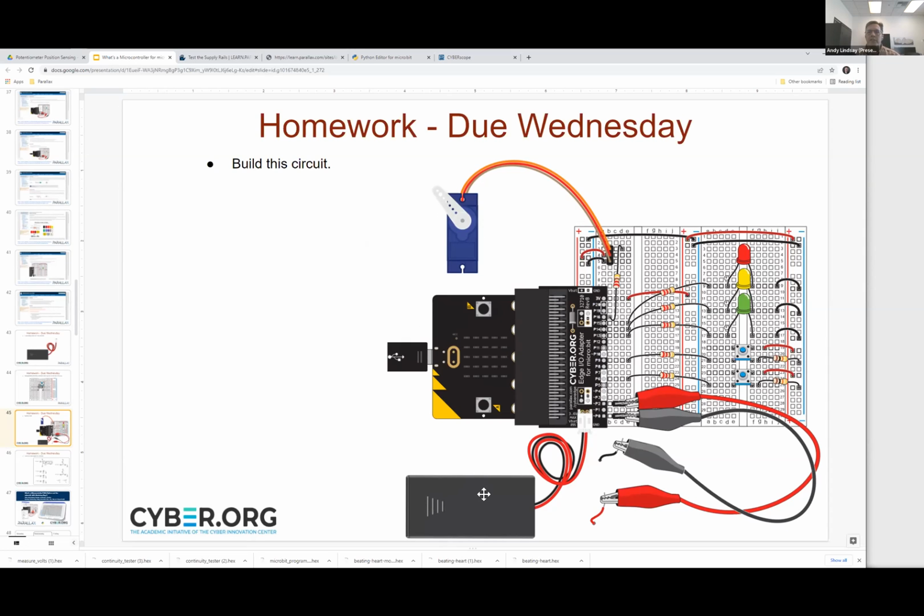The other thing is, if you're at all iffy about electrical or electronic connections, preferably everybody, especially remember that this is not right. These colors are backwards here. I might try to fix the colors. I'll let you know whether I did that in the picture I send you or not. You want to have the red on the left, not on the right, as it's shown here with the battery pack.